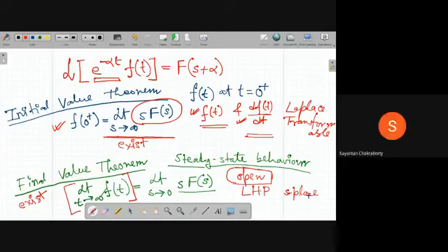If multiple roots are there, right? If there are two or more roots, it will be unstable. Okay, and if they are complex conjugate, then it will be marginally stable. It will give you a sinusoidally varying output with oscillatory output. So, in both the cases, this final value theorem will not be applicable.